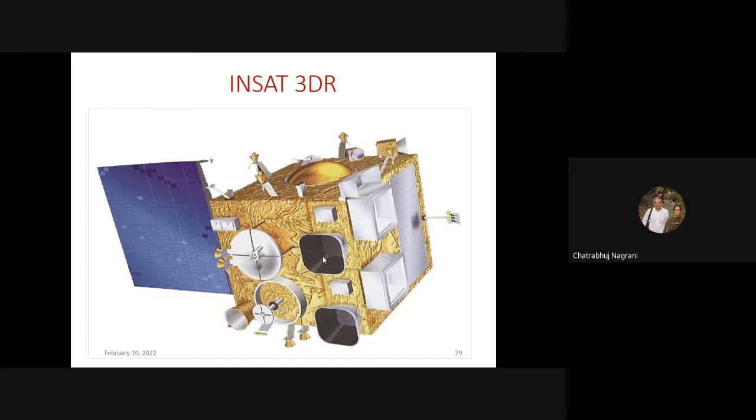Of course, input will be coming from other locations also, but I can deconvolve all that, and I can measure radiation in a given band coming from different layers. So I can generate a vertical profile of the atmosphere. That vertical profile generation of the atmosphere is called atmospheric sounding. So this is the sounder instrument which has 19 channels. The only thing is it has a filter wheel, so it does that sequentially, while this imager doesn't have a filter wheel; it has bands which are there.